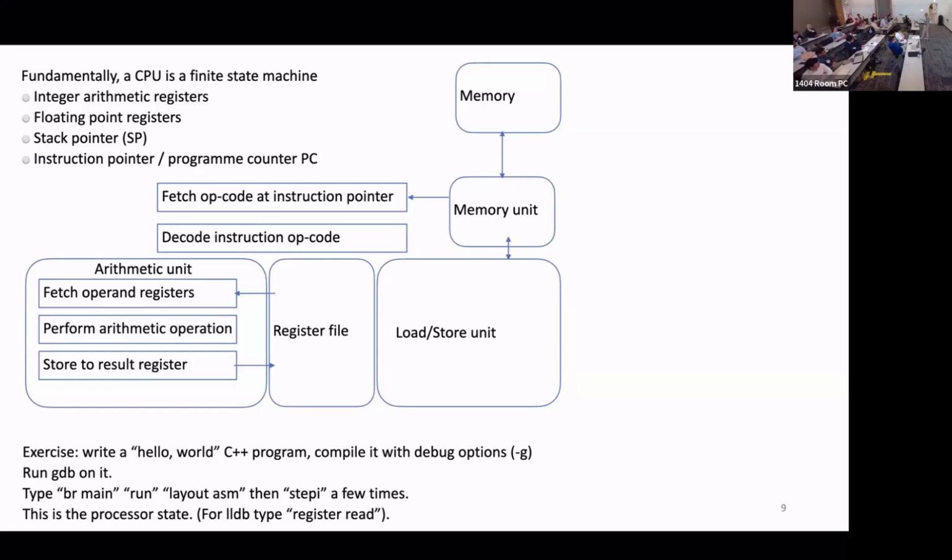It has something called a program counter, which is the current instruction pointer. By default, it fetches one instruction, increments the program counter, fetches, does whatever it does for that. If the instruction is a branch, it then has to change the program counter to whatever the branch says it is now going to. But basically, you think of the program as a sequence of consecutive words.